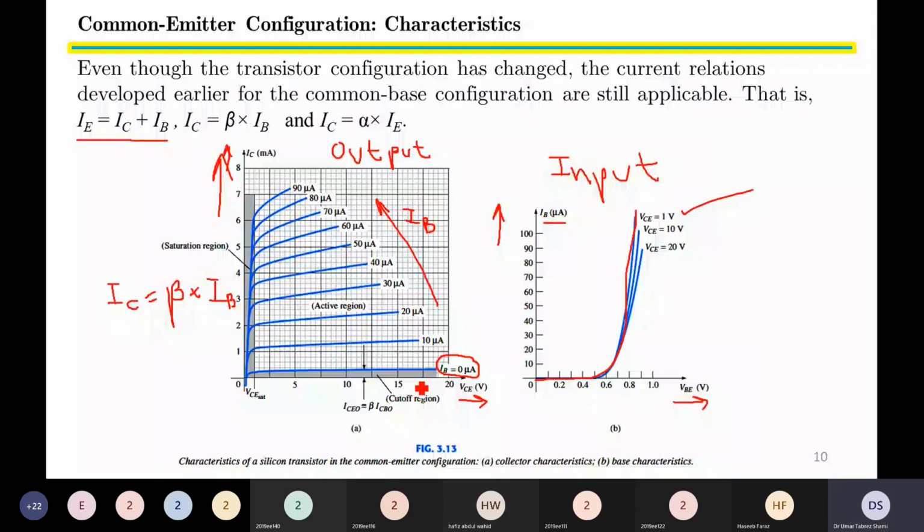However, since we can use a transistor in digital electronics also, while using a transistor in digital electronics, we must ensure that our transistor works either in the cutoff region or in the saturation region. So if a transistor is being used for amplification, it must work only in the active region.